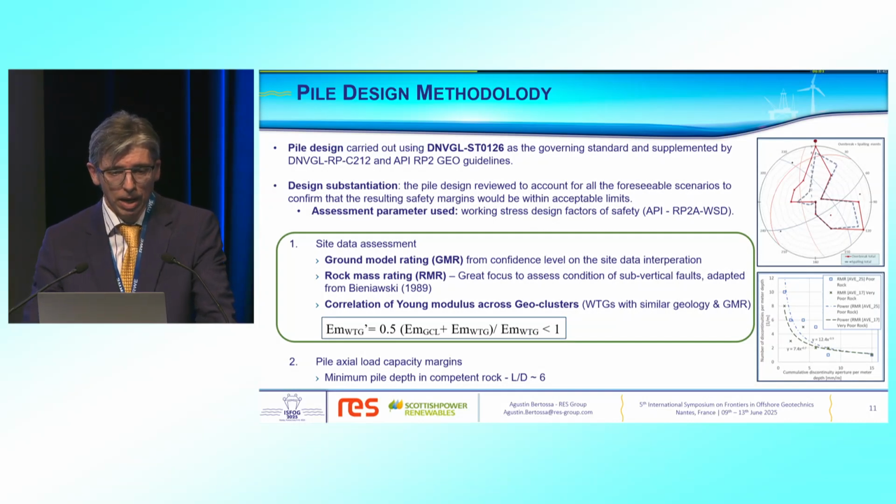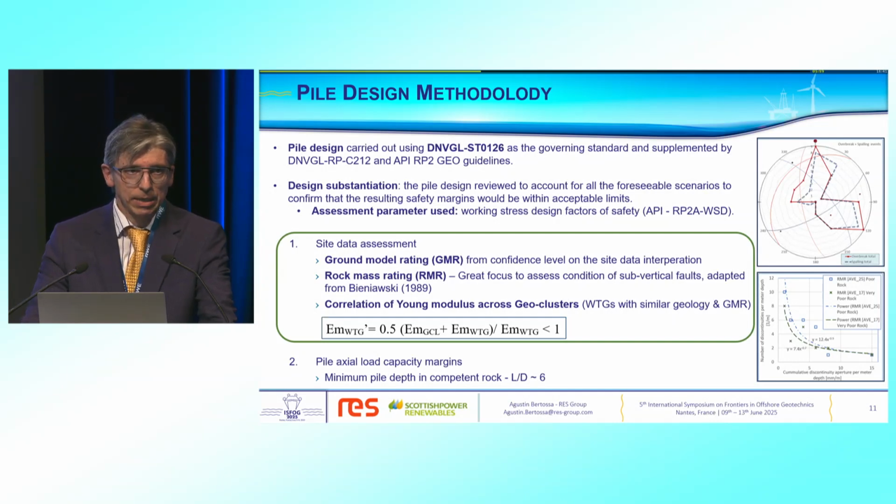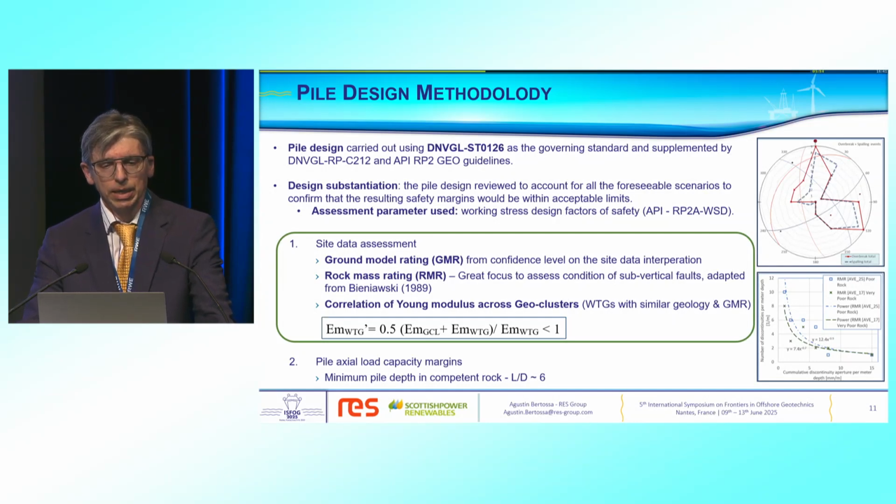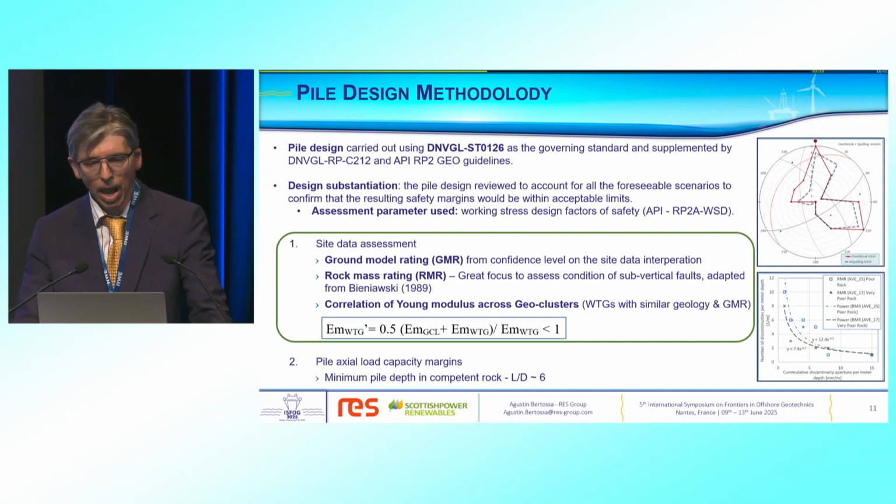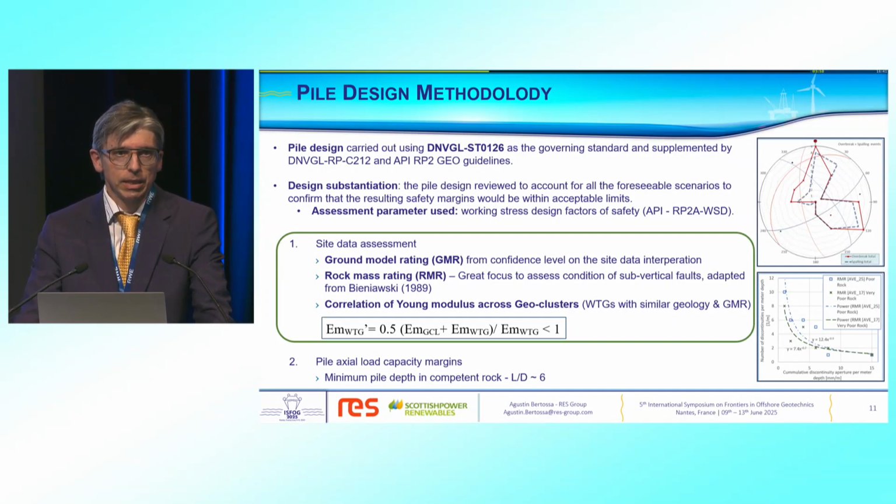So looking now at the pile methodology, the design was completed using the offshore standard, the DNVGL ST0126, and taking the detailed ground model data to define the design basis. But on completion of that, we reviewed the design and we said, well, what if there are things that we haven't covered from the ground model? So what can we think about that could go beyond our knowledge?